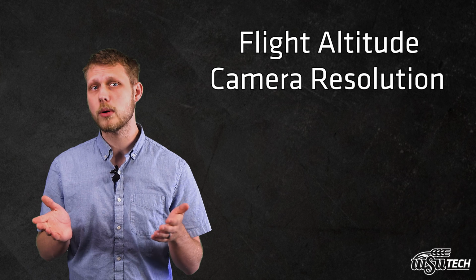GSD depends on 3 things: your flight altitude, your camera resolution, and your lens. Flying lower gives you better GSD, but it also means more photos. It's a trade-off, but when you need to measure surface damage, tighter GSD can make all the difference. Keep in mind what your final product needs to be during the flight planning portion. It really helps with the decisions on GSD.